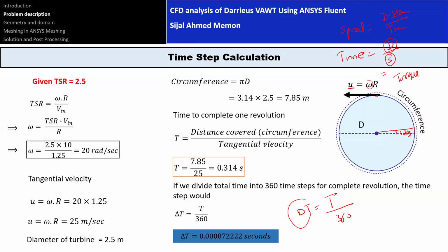Okay. So first time step, it will move forward by 1 degree. Second time step, 2 degrees. Third will be 3 degrees. So what we are doing here is, for example, this is a wind turbine blade here. After one time step, say the blade will be here, so we observe the value of this. We will get the solution of the wind turbine at this angular location. So we get the torque value here. We get the torque value at the second angle, the third angle, fourth angle. So we get the torque values on all time steps, and all time steps correspond to their angular positions.